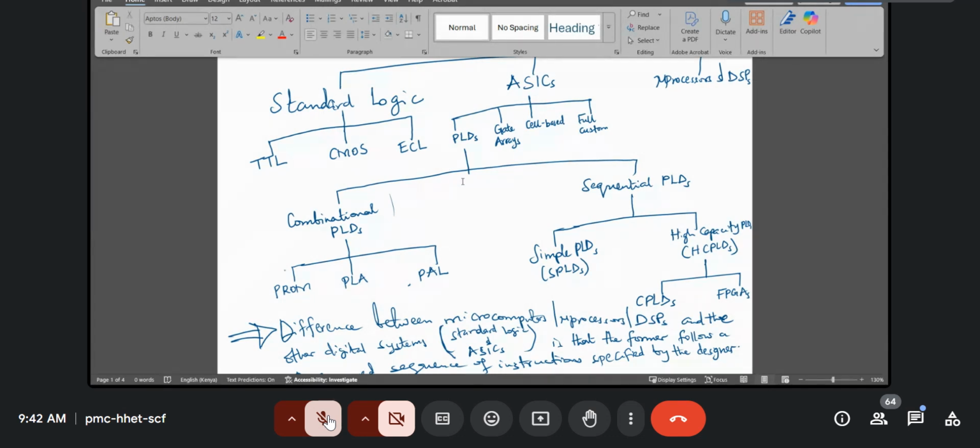I can't remember the various protocols, but how you program the chip is determined by how some bootloader fuses are configured. So there was an option of configuring those bootloader fuses.